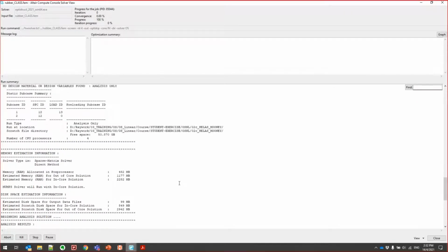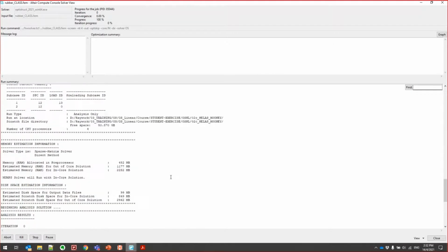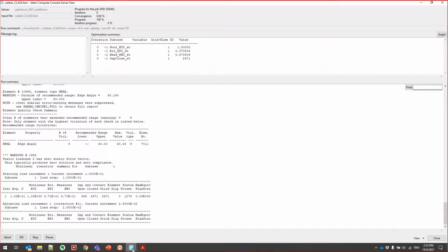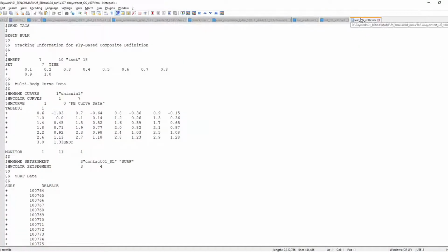Right, there's no curve fitting being done here because we directly put in our constants. Okay, so let me show you an example of the out file where we do a curve fitting. You can see the notepad, right? This is a setup where I only have the uniaxial data. Okay, so it's tension compression data, and this is a stress strain curve.